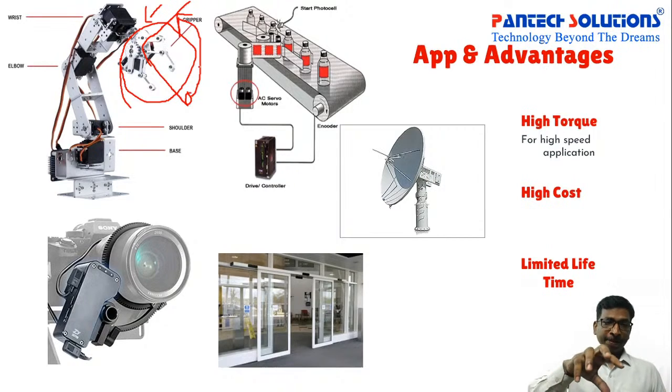And this particular arm will hold the load with a higher torque. So that is the advantage of the servo. Here we can also keep some DC motor, but at low power the torque will be very low in the case of exclusively DC motors. In the case of a servo motor, we can increase the torque, that is the load handling capability, with the help of an additional gearing mechanism. So here a 90 degree controlled servo is required.